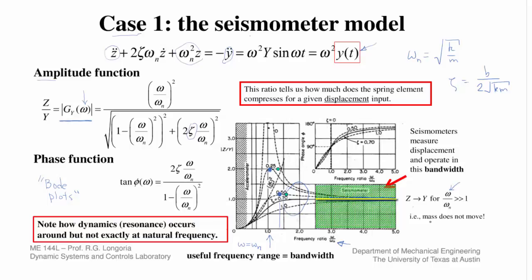And actually what's happening is, imagine you had this mass hanging here, and you can do this little experiment. Get a mass, get a rubber band, and just force it really fast. What starts happening is this mass basically stops moving, but the spring is still deflecting. This is what the sensor is measuring.